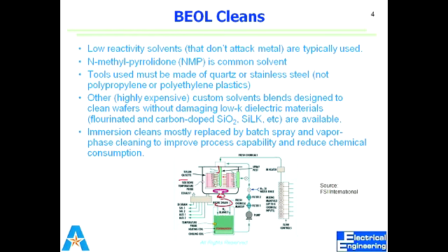When you deposit the first metallic layer, when you make the first electrical connections, maybe a bonding wire or a metallic deposition. So before depositing the metallic layer on your device, the cleaning from the beginning to that step is included in the front end of line. And after the metallic deposition, the back end of line cleaning process starts.